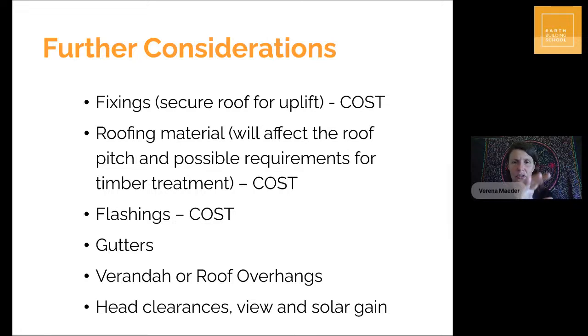So you'll see there are tables for light roofs and tables for heavy roofs, and you choose the one according to the roofing material that you're choosing. If you want to save costs, sometimes you will be able to pick up secondhand steel. There's definitely a cost associated with the whole roof construction, so it's good to price all of that.